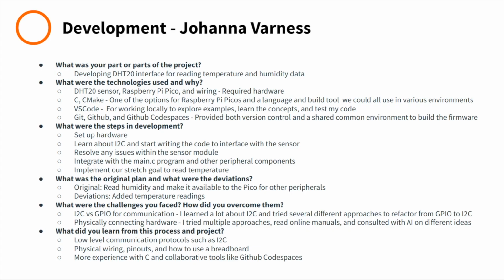Some of the challenges that I faced were initially I got the I2C and the GPIO communication a little mixed up. So I ended up learning a lot about I2C, and I tried several different approaches when I was refactoring the sensor code to implement that I2C protocol. I also had some issues physically connecting my hardware. I thought it was all set up, and then it turned out that I did have my pinouts a little bit wrong. So that one took a lot of trial and error and a lot of reading online manuals, and I even consulted with AI a little bit on that one.